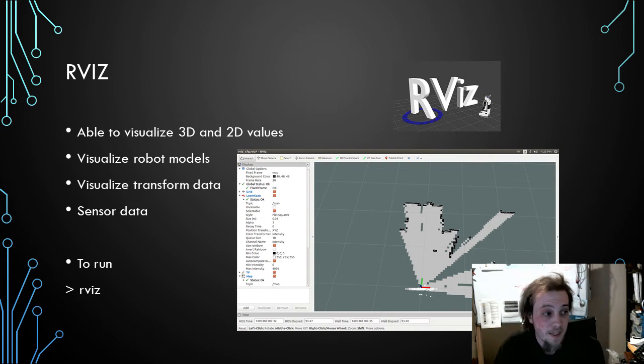Now, further from this, RViz allows us to display a range of data from different sensors, such as distance to an object from, say, a laser distance sensor, as shown here on the slide. Further, it could be a point cloud from, say, a Kinect, or just video data streamed from a robot is able to be displayed here. So we don't need to create these tools, they're already there, and so we can use them for our visualization.